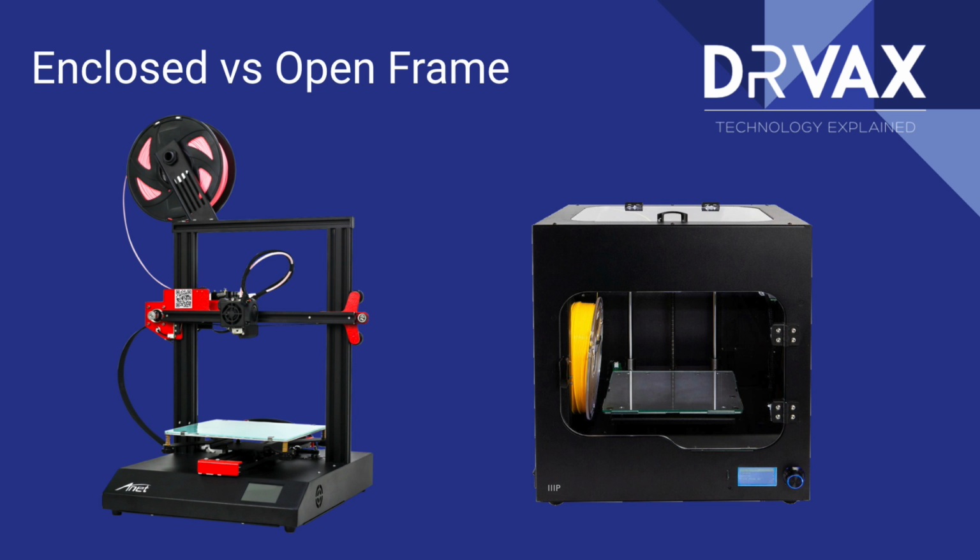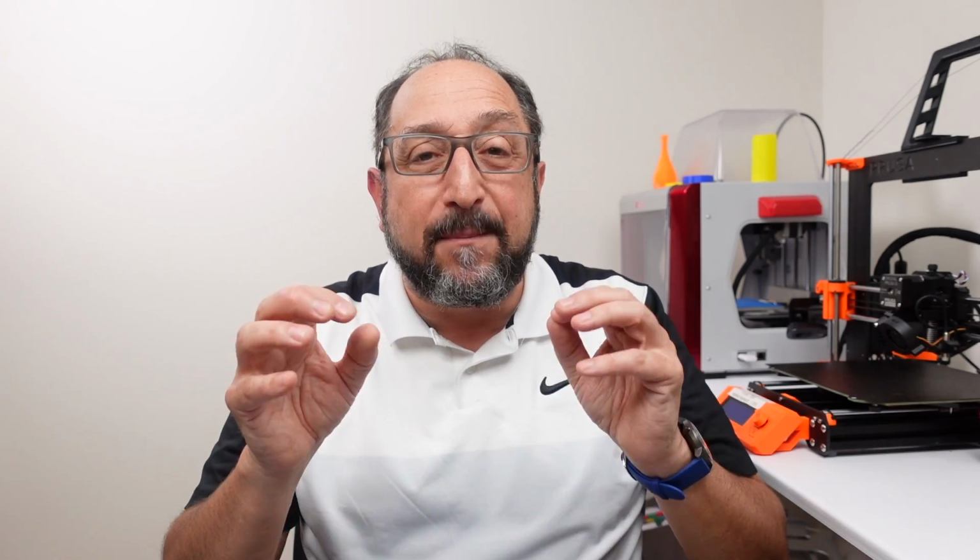Now, fully enclosed or open. In theory, fully enclosed is always better. You get a uniform temperature inside, and it's quieter. Sounds all good. In practice, I don't recommend fully enclosed printers for most people new to 3D printing, unless you're going to treat your printer as an appliance. And the reason is it's hard to get to stuff to adjust it.